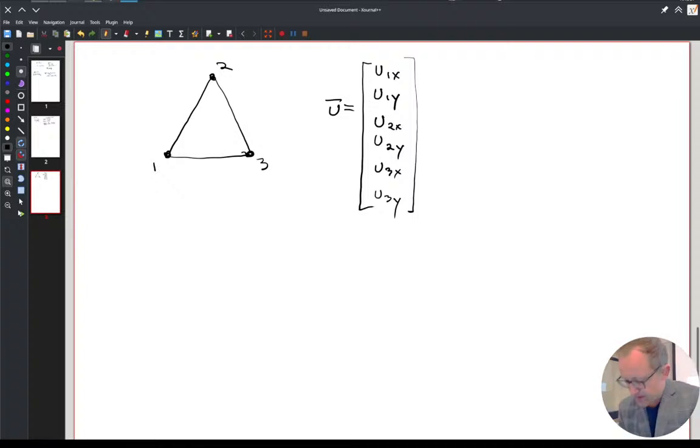So right now, if I say this is my structure, let me apply an F here, an F there, and a 2F here. Technically, I've satisfied the sum of the forces equals 0, but my stiffness matrix is going to be singular. We end up with that same problem.